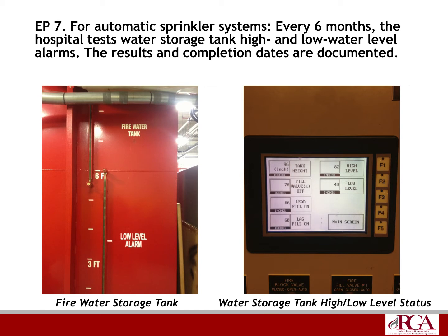So if that's the case, which is typical, then it's every 6 months. It's a semi-annual test. But please note, like I said, if they're integrated into your fire alarm system, and that means they're going to produce a supervisory signal, if we go back to EP1, that means they would have to be tested quarterly. So it kind of contradicts in a way, but if you don't have it tied into your fire alarm system, you're okay with doing the semi-annual test, and that's a storage tank high and low water level alarms. You have to have that documented and inside your documentation, whether it's electronic or binders.